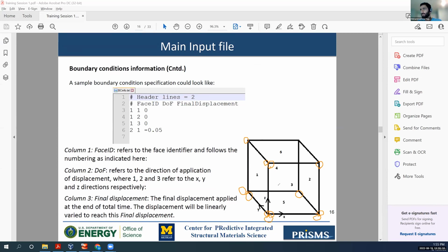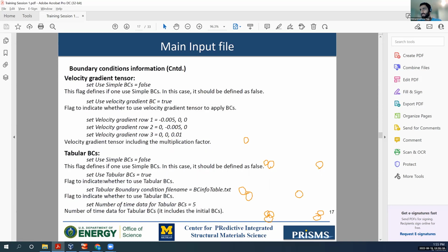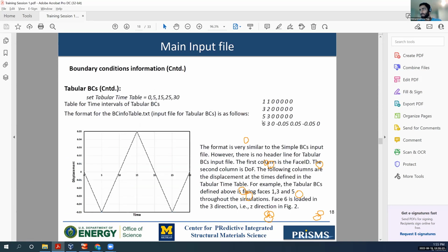And then you're applying, not uniaxial, you're actually applying loading along face 3 along z. So it's kind of uniaxial along z-axis, and it goes back and forth between -5% and 5% if you have a length scale of 1. This is the displacement you're actually applying. It starts with 0 and then goes to -0.5 and then all the way to 0.5 and then goes back and forth.